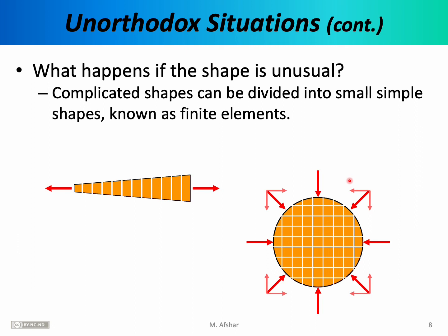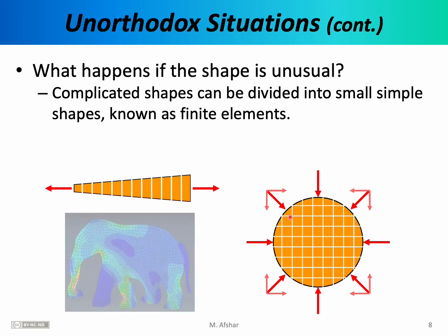Once again, a relatively complicated situation involving a sphere and diagonal forces can be reduced to basically a simple situation involving cubes and simple forces along the horizontal and vertical directions. One would then calculate the bulk deformation of each individual cube, add all of those changes in the volume together to find the net change in volume of the sphere.